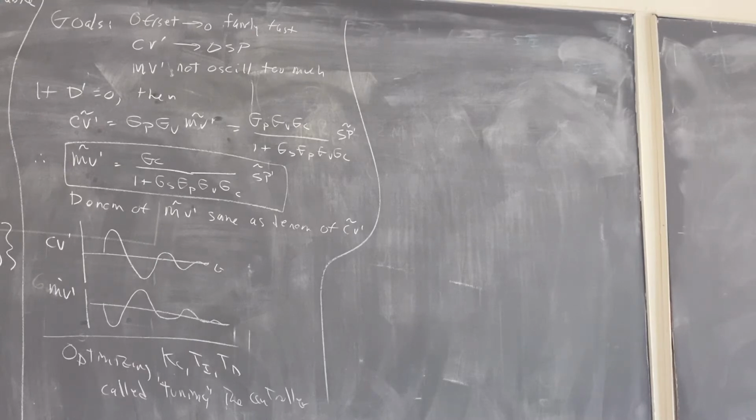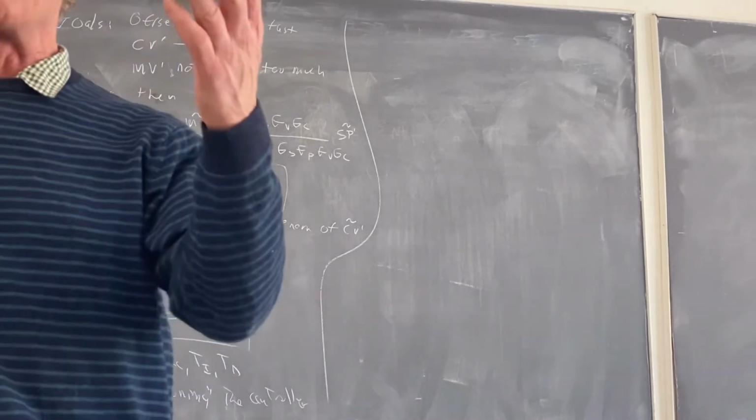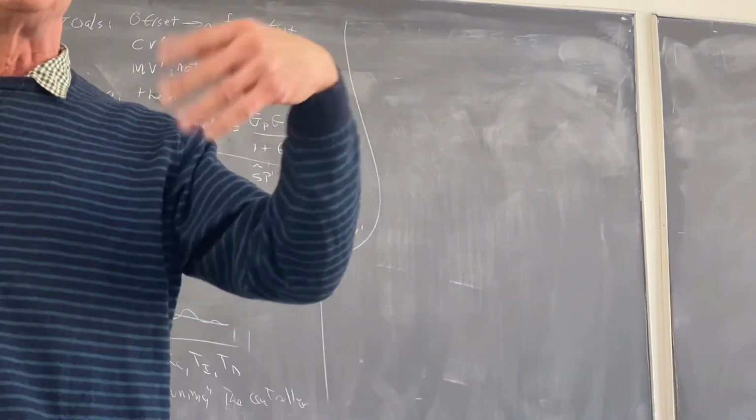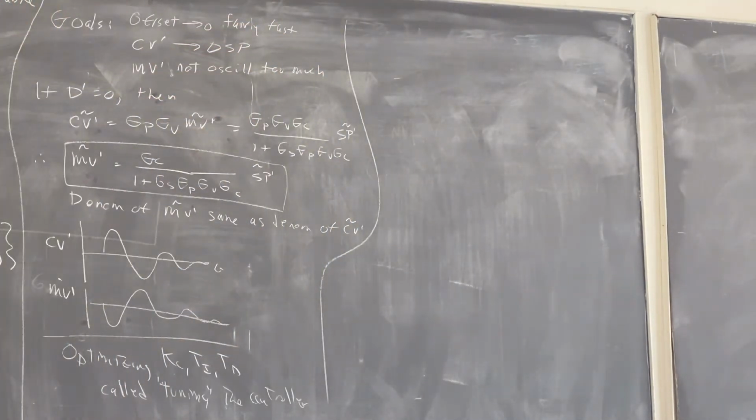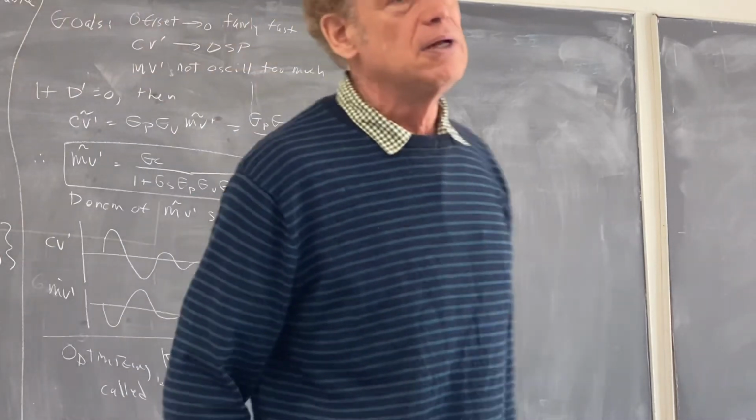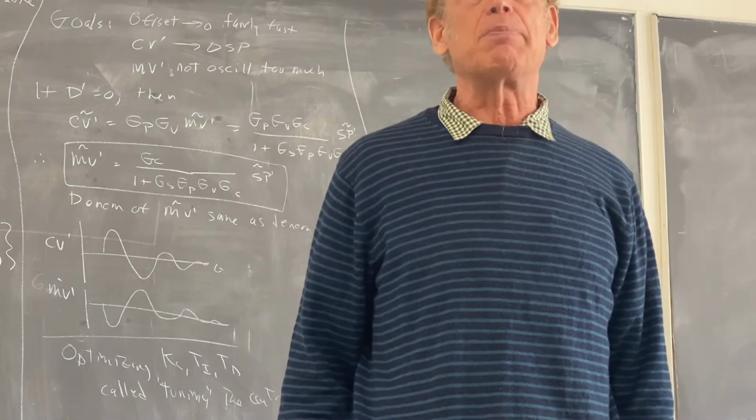Or if I change the set point, generally I'm not changing the set point by 100%. I may change it by 10%. That may be enough to make the linearized model not that great. Moreover, we usually assume that parameters stay constant when I change things. Well, if I change the temperature, or if a disturbance changes the temperature, CP may change, CV may change, delta H may change. There are all sorts of approximations in the model that make our models not perfect.